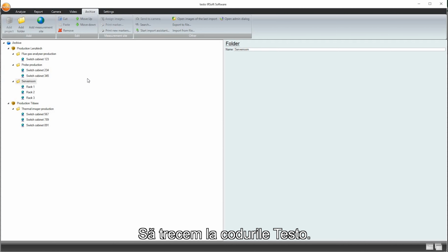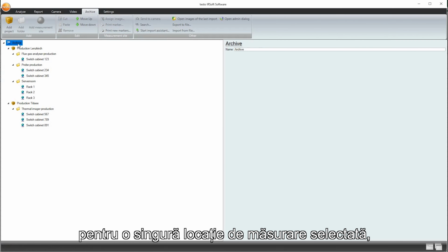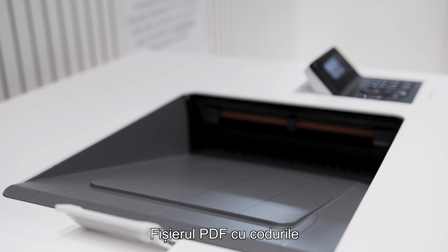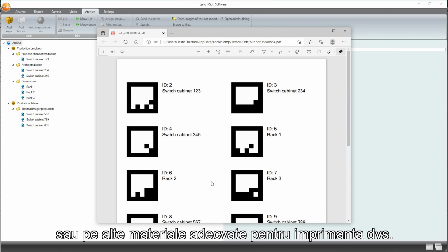Now to the Testo Codes. These are crucial for the Testo SiteRecognition to work. You can either print a code for one selected measurement site or print out the codes for all new measurement sites at once. In printing, the codes are converted into a PDF. You have the choice of A4 or letter format. The positions of the individual codes are freely selectable. The PDF with the codes can be printed out on a printer. It can be printed on conventional self-adhesive labels available in retail or on other materials suitable for your printer.